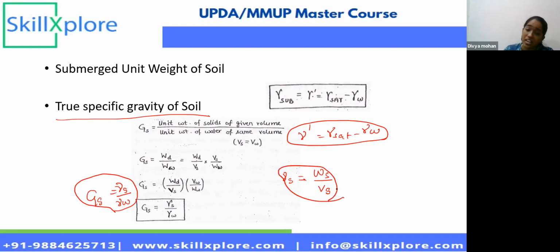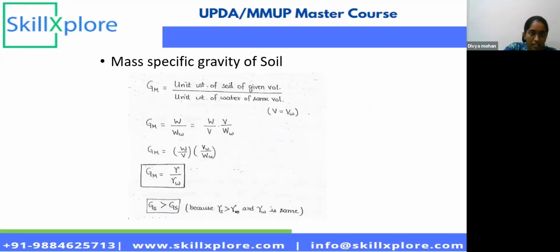It will not change in any condition. Even if you add water into the soil, this parameter will not change. However, the mass specific gravity is an apparent thing which will change accordingly. It will change for a particular water content and a particular void ratio.